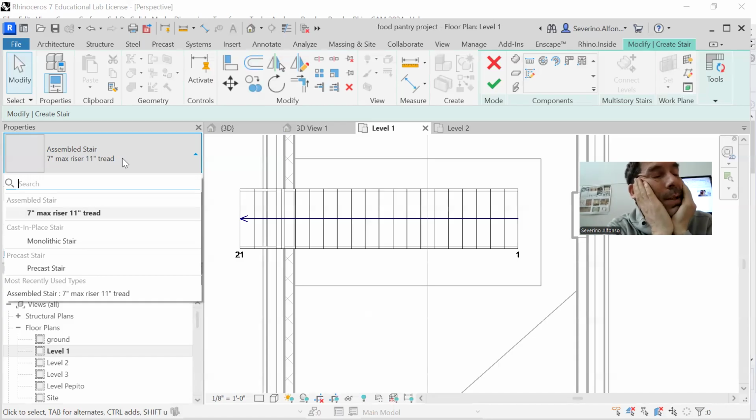And then the precast, basically outside of the site in the factory or whatever it is, they do the pouring and so on. They put it in a truck and they bring the pieces of the stair to you, and with a crane or whatever they place it. It's more detailed and more carefully designed and fast to install, but more expensive because highly qualified workers are involved, high expertise of a company, et cetera, et cetera. Okay, so those are the three.